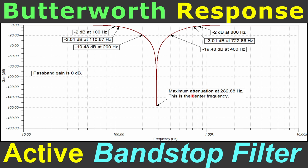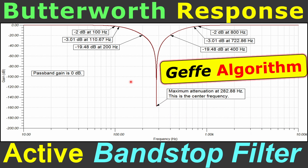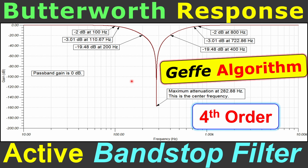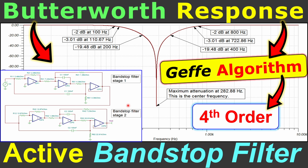Welcome to a new video about analog filter design. In this example we will discuss the active bandstop filter having a Butterworth response characteristic. We will use the Geffe algorithm as we have done for the band pass filter realizations. There will be a fourth order band stop filter design, and we will see the circuit realization also, and we will verify these of course in the TI SPICE simulations after we have done the step-by-step calculations before that.